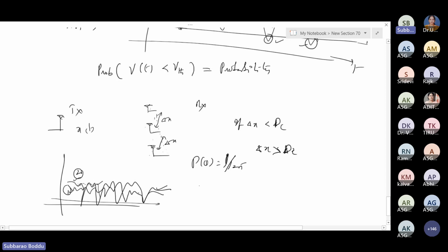So we are not using extra power here. We are not increasing the power. We are not using any extra time, in terms of time T1, T2, or in terms of frequency also. Each receiver branch has its own receiver circuitry. The only thing you may worry about here is that the receiver cost would go up, and the receiver power consumption would go up, because we have to process many signals here.